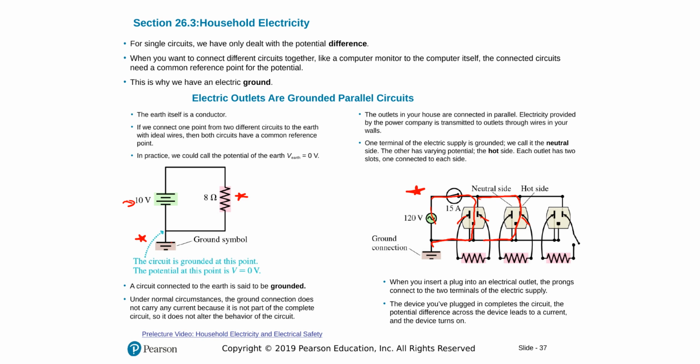So the more devices we connect to the outlets, the more current we draw, because as you folks remember, hopefully, from parallel arms, if they have the same resistance, they will have the same current, but they always have the same potential difference. So they keep drawing more and more current as we add more devices to the system.